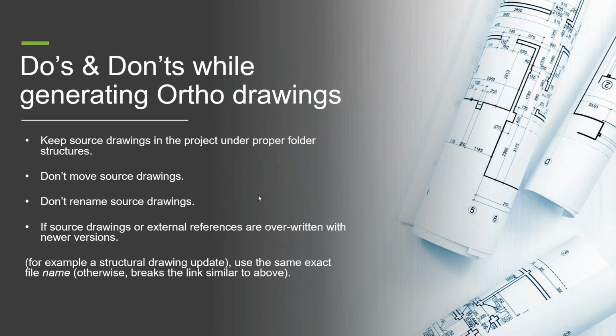So it expects that the blocks that are in your ortho point to database records, which point to valid IDs in the 3D model. If you rename your models or try to take an older ortho and copy it into your project, you might end up with getting disconnects there because the IDs won't match in the database, and so it won't be able to update the ortho. At that point, it loses its connection.